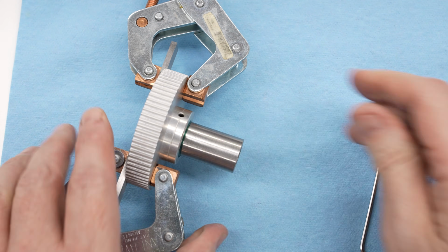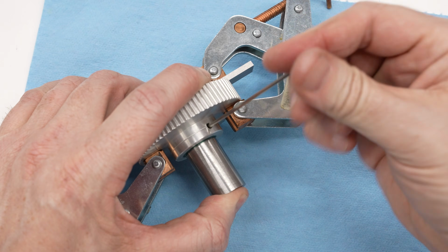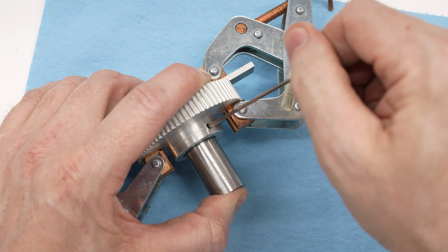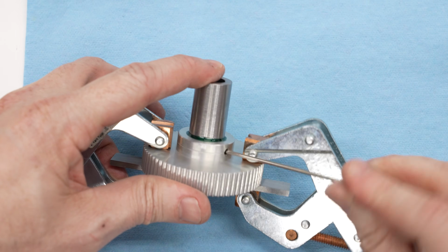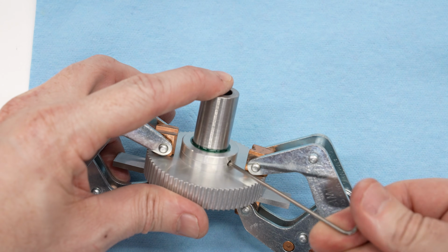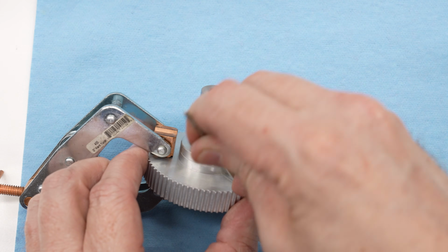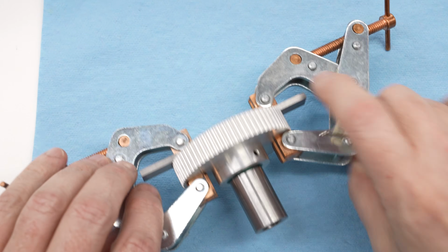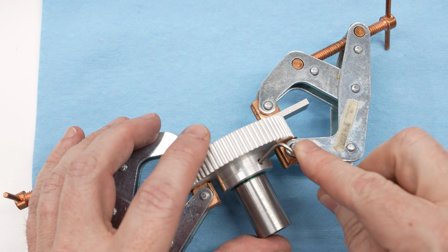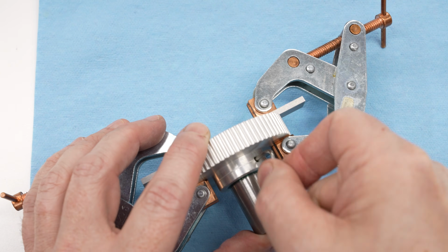I can see a nice bead squeezed out on this side, and there's a nice bead squeezed out on the other side, so I'm pretty sure I've got this completely covered. And I'll go back through and just lock down these two set screws. We're not actually going to use these in the end, but since they're here, I'll use them to lock the parts together so that the retaining compound has a chance to set, and I can continue handling the part without risking breaking it free or misaligning it.